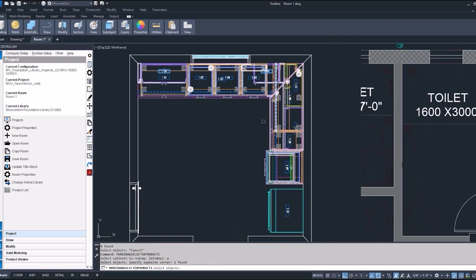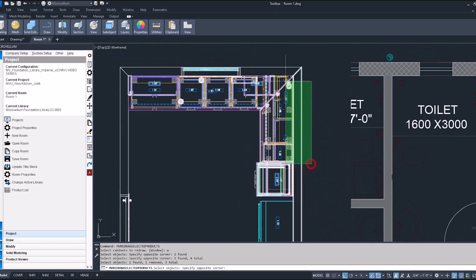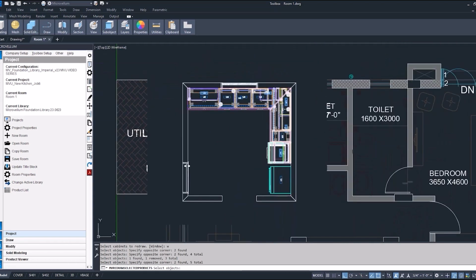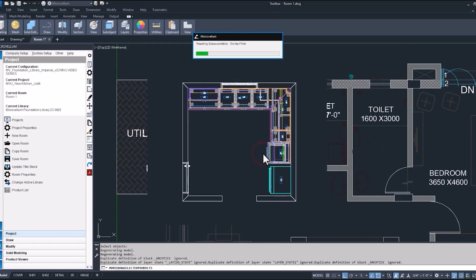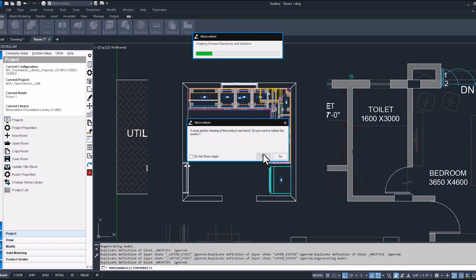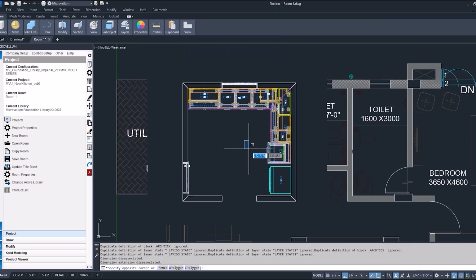Remember, the window allows you to highlight those item numbers. And for the tall, if you have something in there that you don't want, just hold down Shift and left click to unselect that. Get the other uppers on elevation B, and yeah, I think that's it. So we'll redraw those. I want to redraw the plan view because we want to update our shop drawings along with this, but I'm not going to redraw the cross sections for right now. We'll go and do those individually.